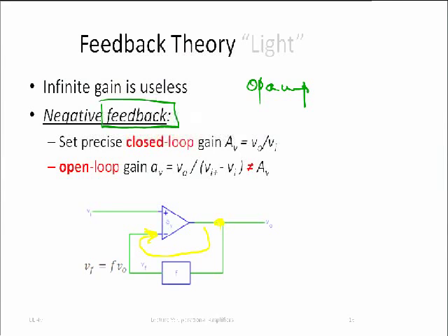That's the gain of just this box here without feedback around it. So that would be the difference of these two voltages amplified. And so that's the gain AV. That's V out, this V out, which happens to be the same here as the overall V out, right? Divided by the difference of these two voltages, these two, right? That is the little AV, and it's infinite, right? So that's called the open loop gain, and it's of course not the same as the closed loop gain, okay?